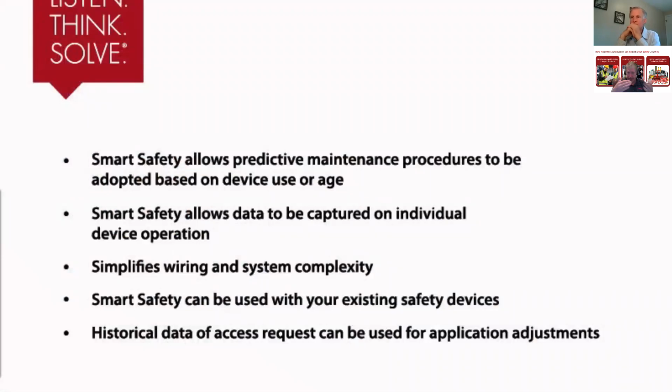And again, that's just one example of where that information becomes useful. Another information use that I would say is, we've had actual applications of this occurring where we track how many times a safety guard door interlock is opened, and we expect that it only is opened 2 times a shift, let's say, to change out a reel of tape that's on a box taper, right? So suddenly that door becomes opened very, very frequently.